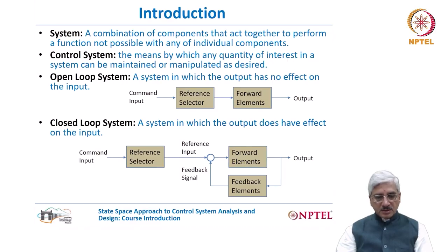The closed loop control systems may be costlier compared to open loop systems. They may be more complex than the open loop systems. However, they overcome the drawbacks of open loop systems. They are more accurate and they are less susceptible to disturbances or noises.